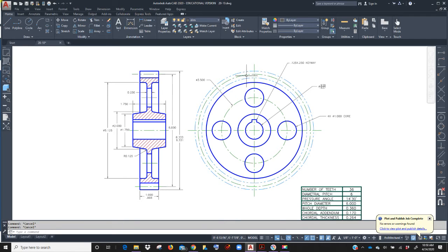So once you get those numbers, those diameters, you draw those in, and then you adjust, you pull things over, pull it over, there's your center line, there's your outside diameter, and you adjust top and bottom of this section. On the next part, you're going to do the same calculations, but then your PD, your OD, and RD will change, and you will adjust those 3 circles and adjust your drawing. So once you draw this base, everything's the same, okay?